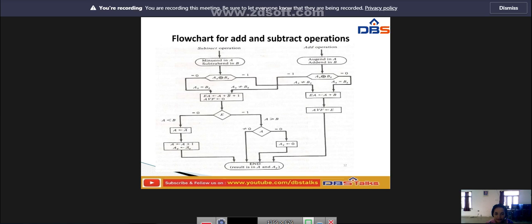After that, we compare A and B. A 0 in E indicates that A is less than B. The number in A is the correct result. If this number is 0, the sign of A must be made positive to avoid a negative 0. A 1 in E indicates that A is greater than or equal to B, and the number in A is the correct result.